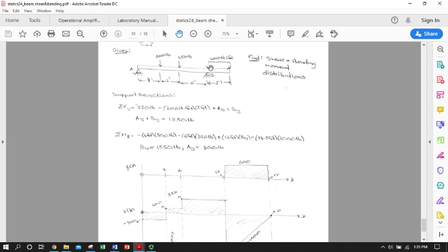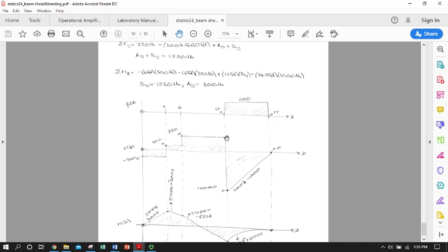Okay, then we've got two things that happen. One is we've got a huge upward point load coming from roller ball B. So at just past that, but before we've actually really picked up anything from the distributed load, the shear force is going to shoot way down negative just to balance the support reaction at A, the support reaction at B, and these 2 point loads.